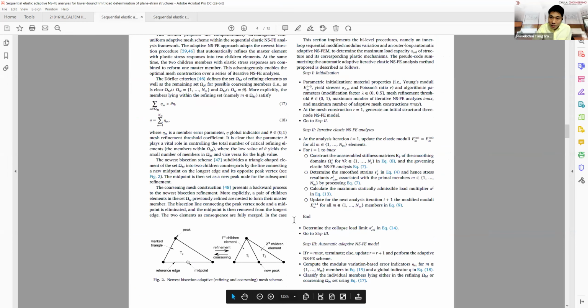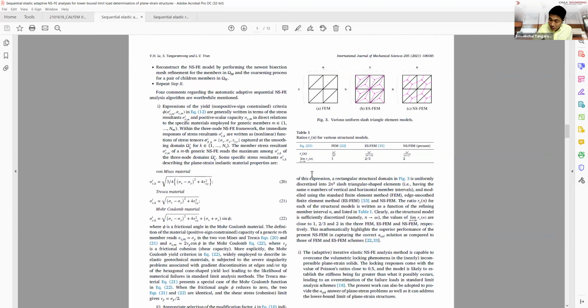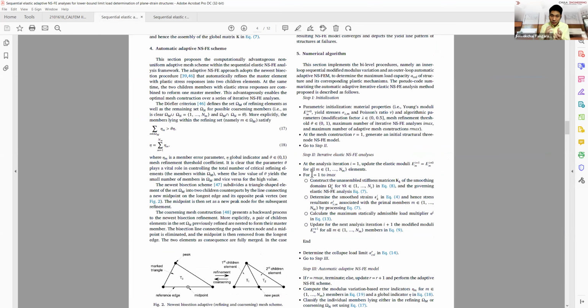The smart mesh means the mesh can subdivide itself, so it can adjust the number of the mesh itself. The element that I propose is in the active area, where you have a huge intensity of stresses, a huge value and huge variation, changes of the stresses in some small areas. It requires a lot of mesh in those areas.